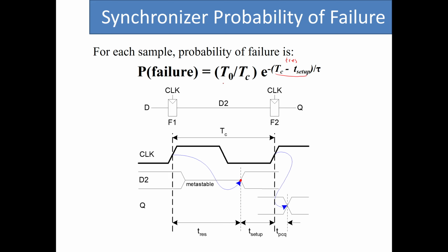So again, this is a probability. Depending on the value for the time that passes, this probability would go down. So if you wait, let's say, 1 second for a circuit that works with a 5 megahertz clock signal, after 1 second it is definitely resolved, right? Because you have waited a very long time. But when Tc is in the order of several nanoseconds, then the maximum amount of resolve time is going to be in the order of nanoseconds too.